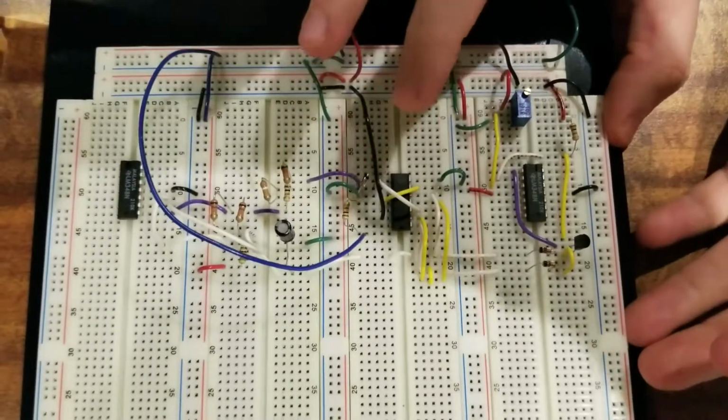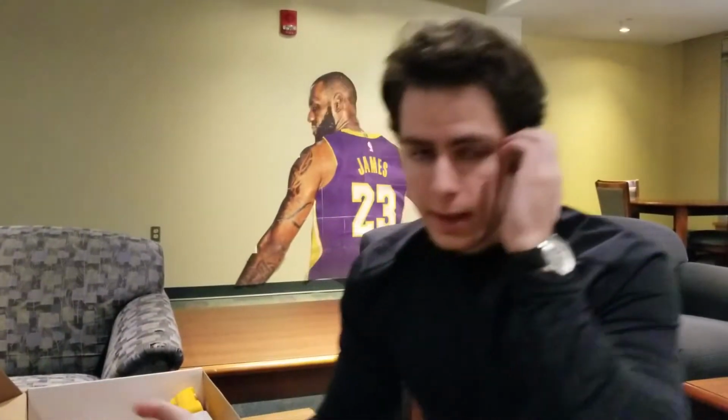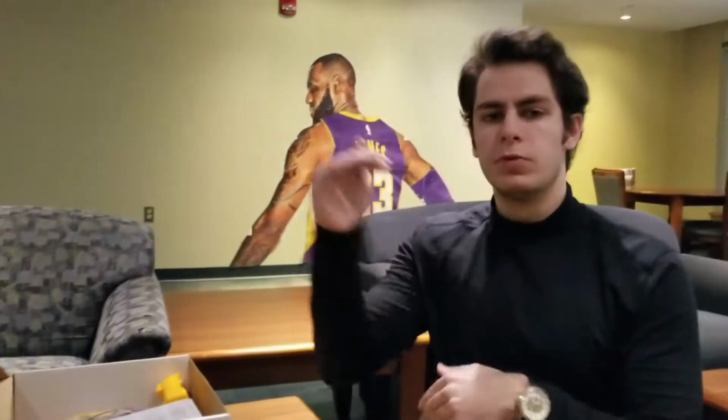So what the VCO as a whole does is that it allows you to feed in some constant DC voltage to the whole VCO, and then give this oscillating output depending on the states of the current mirror and all the other sub-circuits that work, effectively changing a DC signal into an AC signal, given which the two voltages that will come out from the AC signal correspond to the real voltages that are given by the design of the VCO.